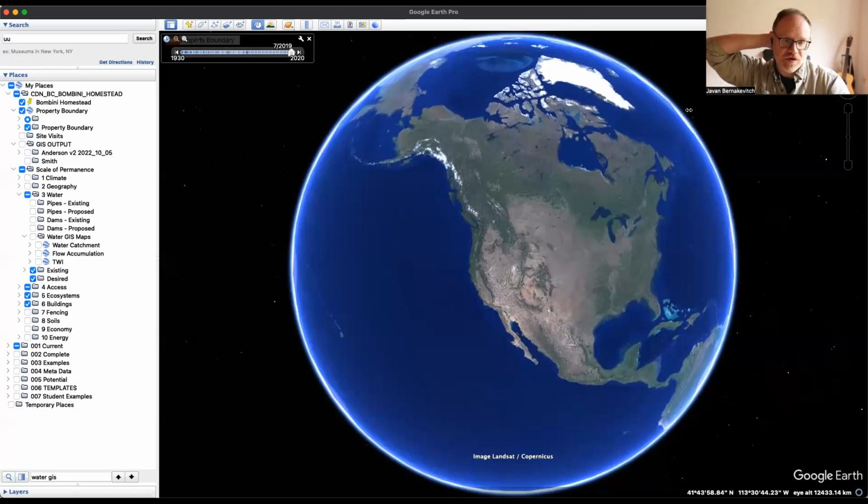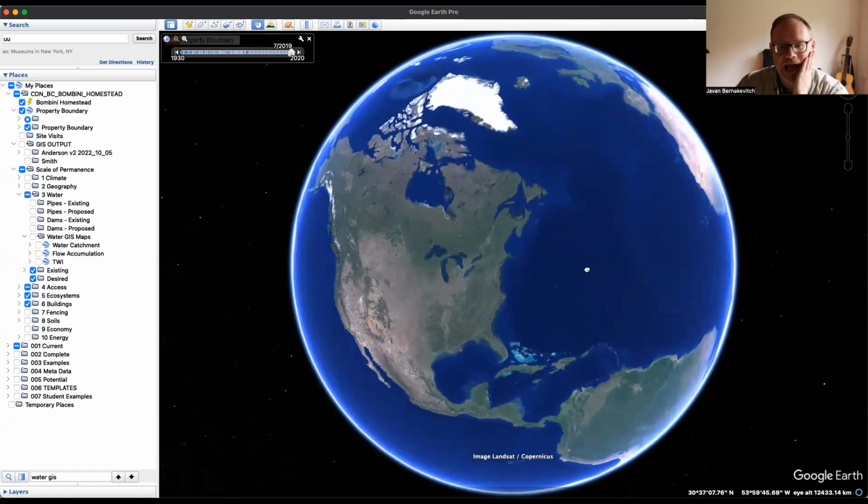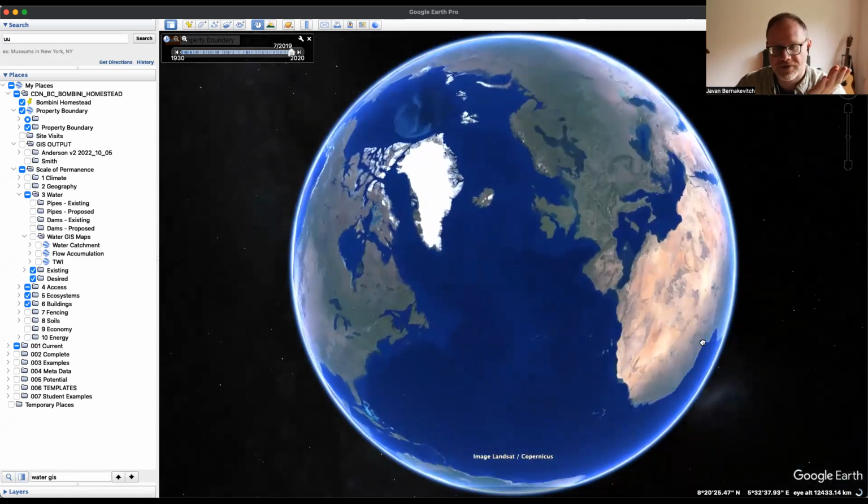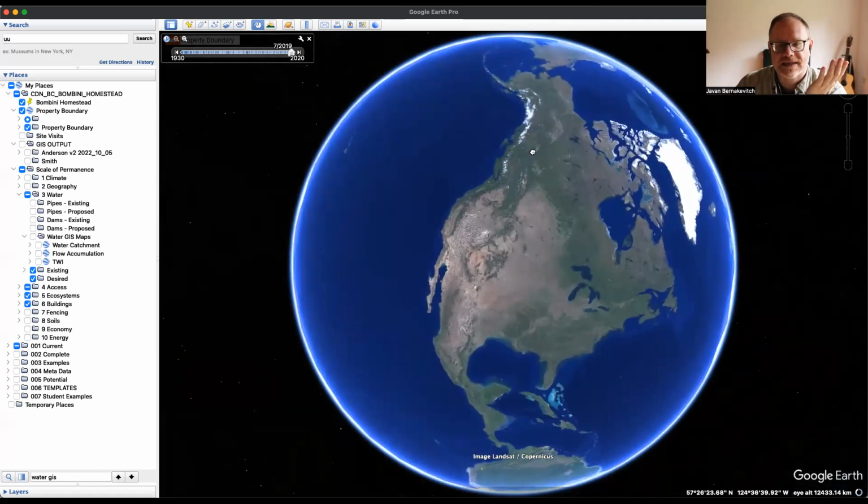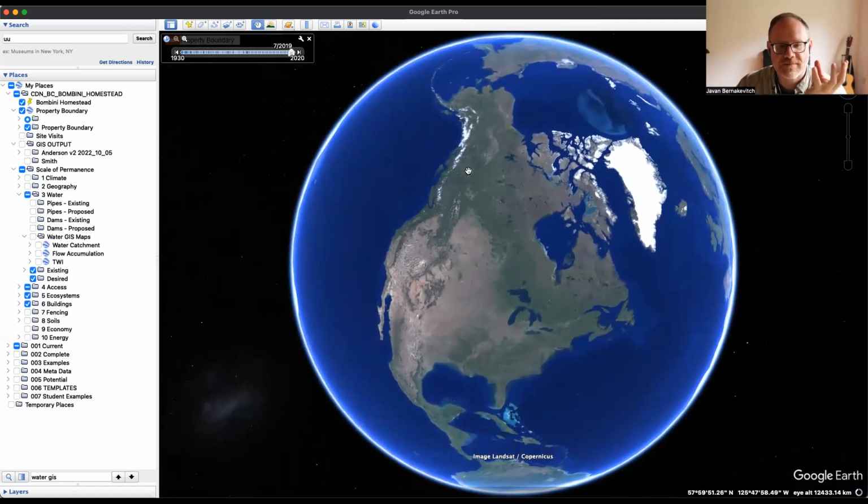This is because the majority of the information Google Earth Pro is using came from the Shuttle Radar Topographic Mission, the SRTM 2000 mission that happened in 2000 through NASA. Basically, they ran the world with LiDAR. When they were shooting the laser down from the satellite, it was a 30-meter pixel, which means if the information, specifically the z-axis, the altitude, is less than 30 meters, which most of our sites are, then that data needed to be interpolated, which is that wonderful scientific word for guess.